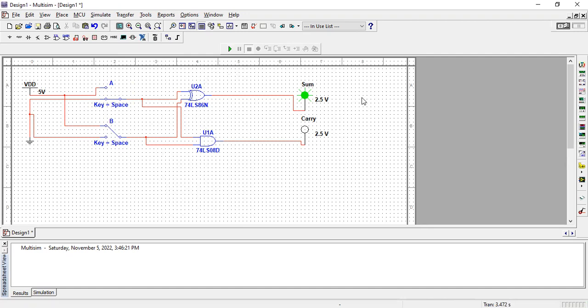For that, I'm just doing a simple modification in this circuit so that I can explain from a basic modification, because we have seen that when we talk about the half subtractor, we have almost similar equations. In case of borrow, the borrow is A complement dot B. It means we have to just make a complement input from over here.